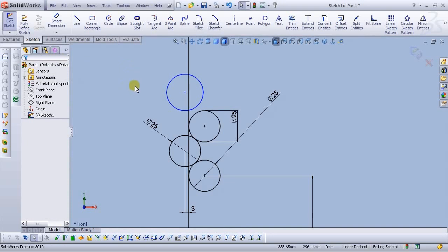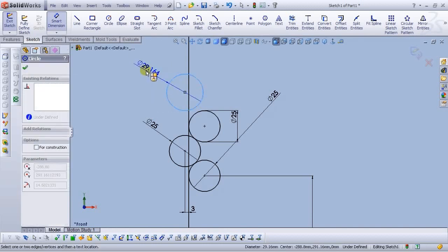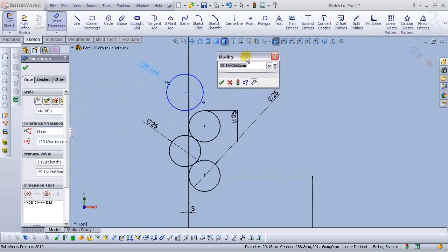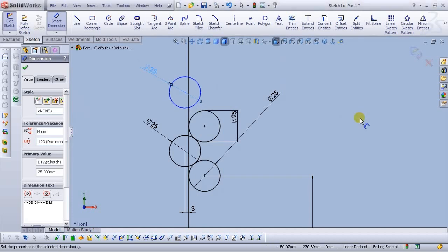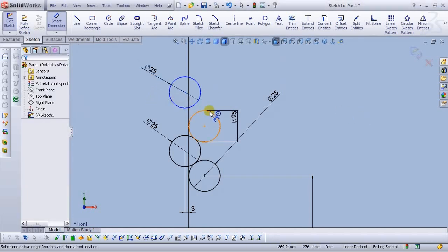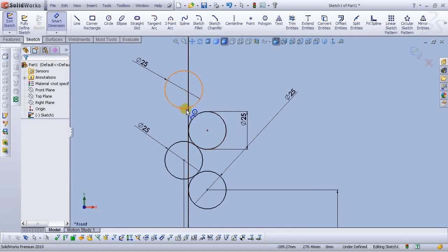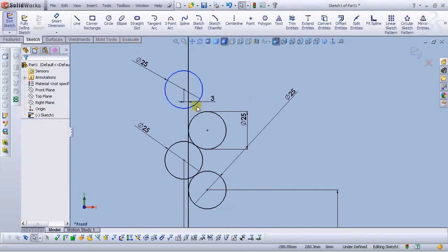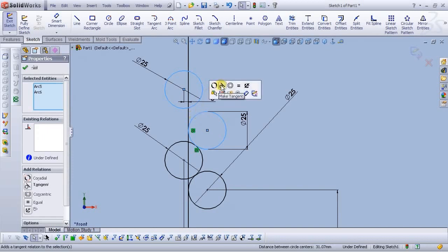Let's mark dimension. If you use Solidworks 2010, you can use the shortcuts for Smart Dimension. You can see this for sketch, convert lines, and everything. Let's click Exit. By holding the right mouse click, you can hold and go up and then choose whatever you need. You need dimensions, go to dimensions. You can Smart Dimension like that. It's much faster and convenient.